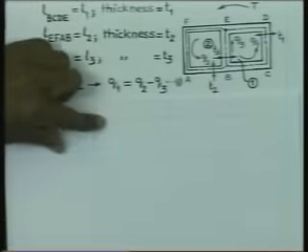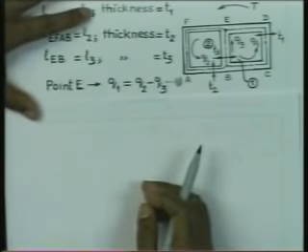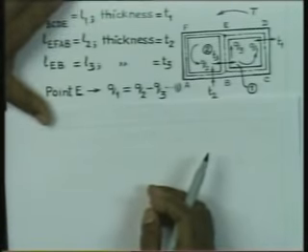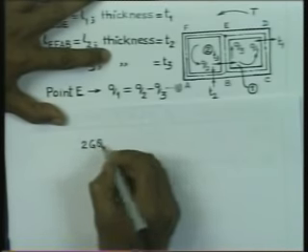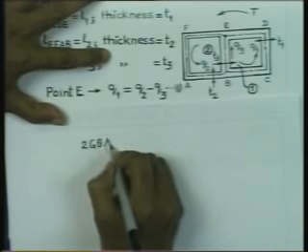The whole section is going to rotate as a single unit. If we consider that the angle of twist per unit length is theta, we can write that 2 G theta into A is equal to the integral of the quantity tau into ds. If I now consider cell number 1, we can write 2 G theta into the area of cell 1,